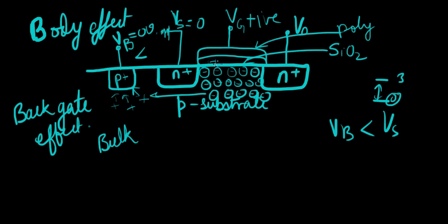For example, if there are a lot of positive charges here, they have to be equal in number to the negative ions. That's called mirroring, right? But now we've not changed VG, but because of the lowering of voltage at the bulk, we are having an extra layer of negative ions. Now this extra layer of negative ions is going to demand more positive charges here to be mirrored, to be balanced exactly. Until that balance happens, there can be no conduction.